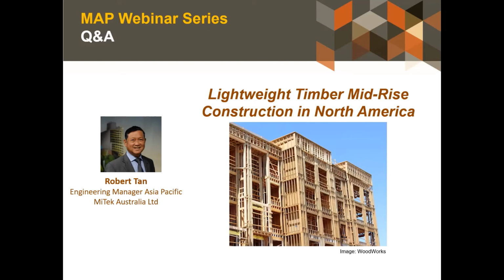Thank you. Yes, to no noggings, and I see that there was another comment about noggings from Len. In response to the use of noggings in Australia, the US building practice has been for claddings fixed to both sides of the wall. Most of their bracing is also OSB to the total wall frame. In Australia, where brick veneer is commonly used with plasterboard only to the inner face, noggings are required to provide the long-term stability. So yeah, thank you, Len, for adding that comment.